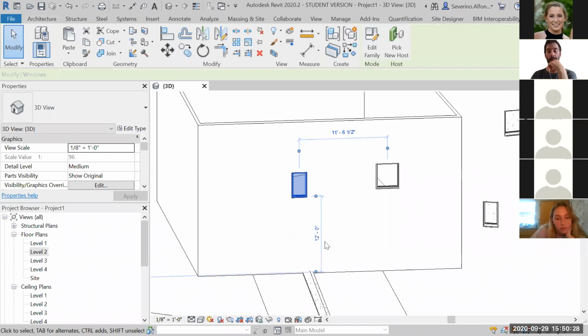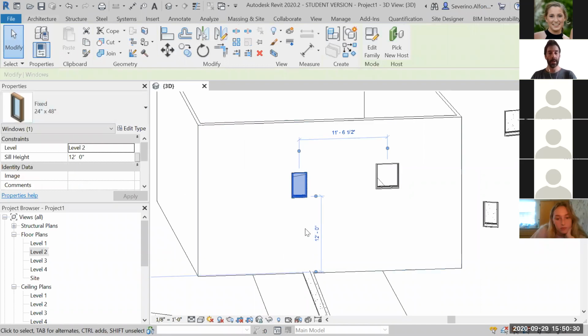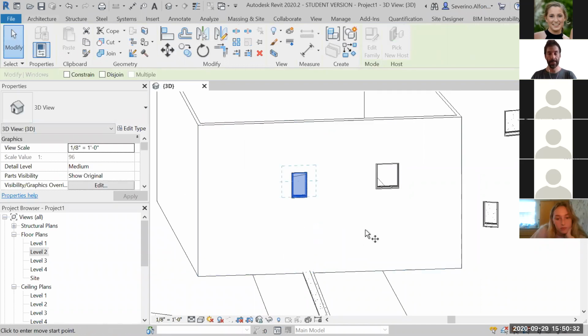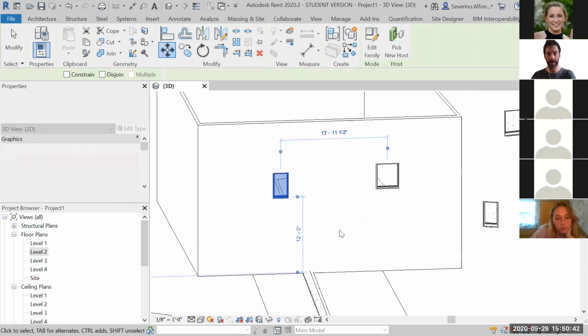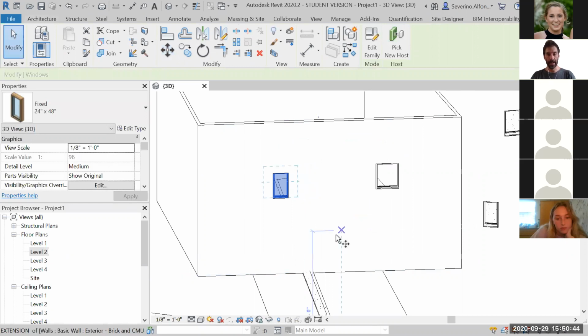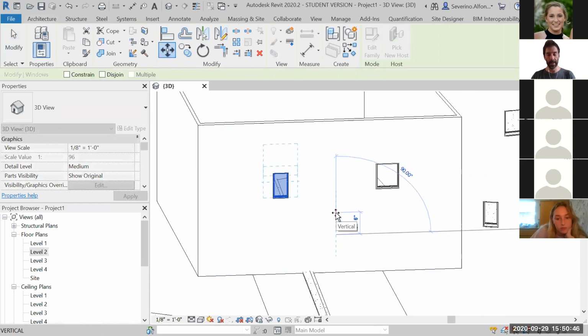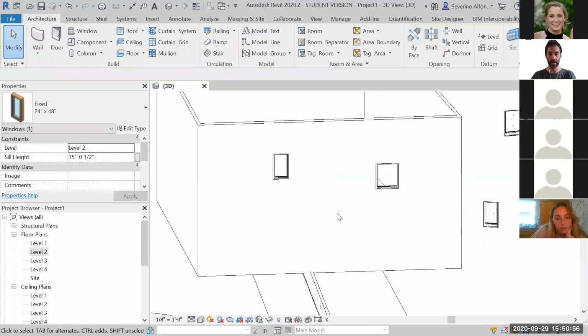Again, you can select windows that we have placed, and you can say MV, click, and then insert the different parameters by just pressing one number, spacebar, and another number. That would be 2 feet and 5 inches. Or MV going up, for example, vertically, and you can say 3 and then 1/2. That would be 3 feet and 1/2 inch. So those are very simple.